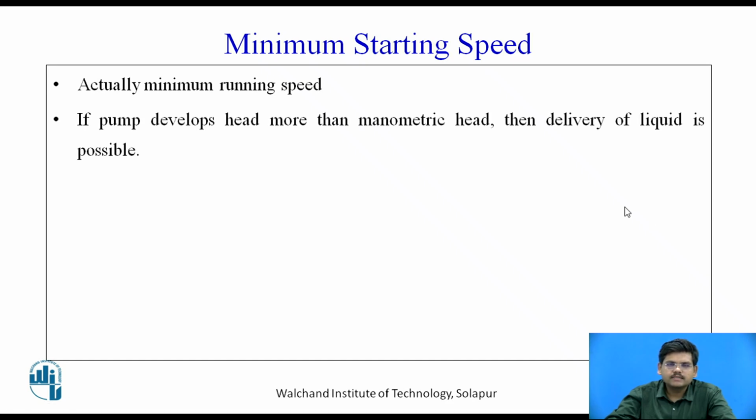If the pump develops head more than the manometric head, that is, if the developed pressure is more than the manometric head, then delivery of liquid is possible. Unless and until the developed head reaches the manometric head or more, the delivery of fluid is not possible. That is, suction of fluid with the help of that centrifugal pump is not possible.